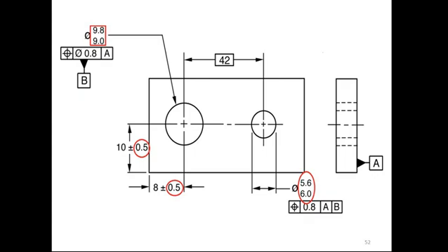So friends, today we are going to see the symbols shown here. Sometimes these symbols are required for measurement purposes, and they are also useful for manufacturing. When someone wants to manufacture this component, the GD&T symbols will be useful. When someone wants to do inspection, the drawing helps them understand what kind of tolerance zones and limits have been given, within which the dimension can be achieved. So GD&T is important both at the time of manufacturing and at the time of inspection.